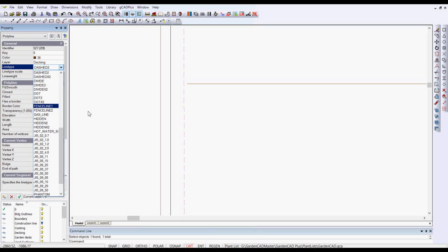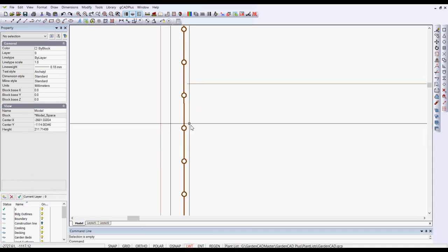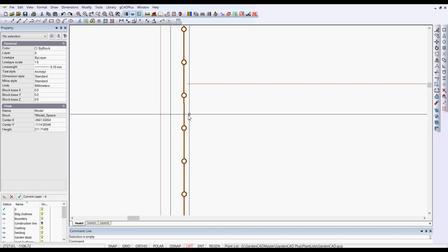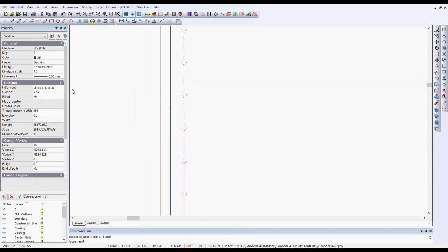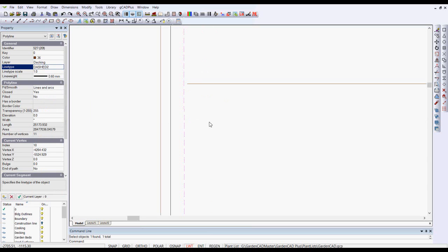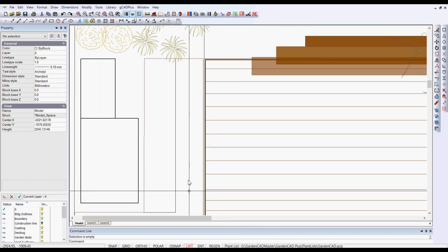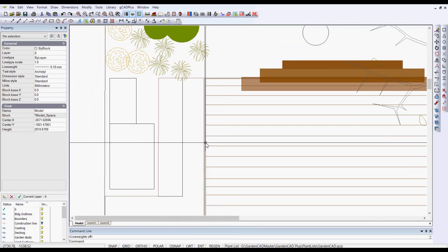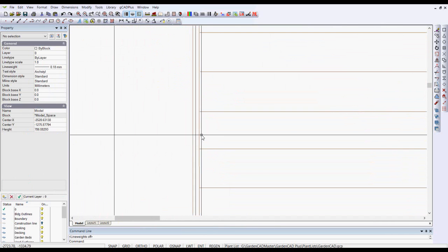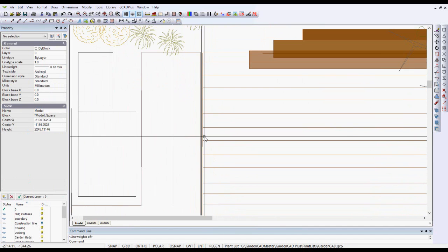So you can set a gas line or a fence line or whatever you want. Let's just see what happens when we set the fence line and we unselect all. Can you see we've got a sort of chain and wire effect? But let's go back to setting as dashed 2, I think it was. There's dash 2. Notice as we zoom out, and I'll turn line weight off, as we zoom out, the dashed pattern doesn't show until you zoom right in.